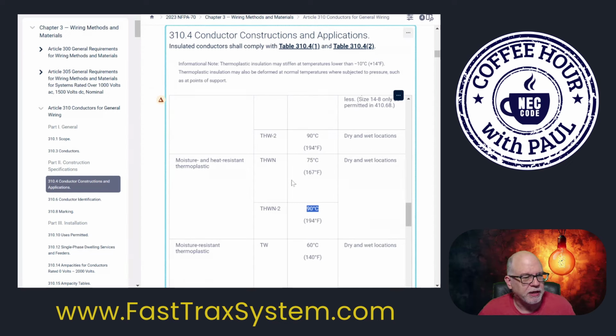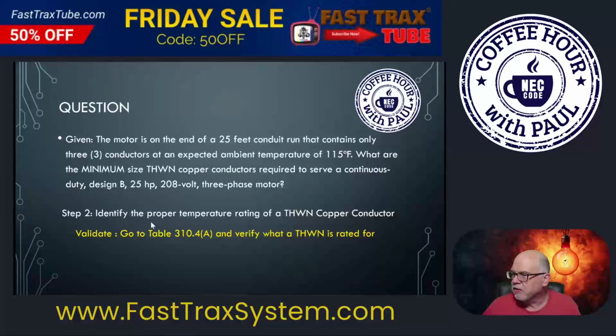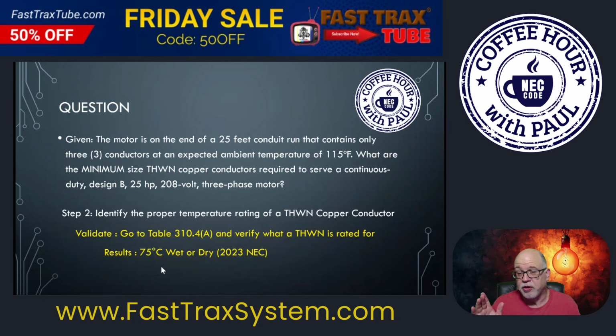So we know what we'll be working in. So we're obviously going to be right here in this 75. Okay. All right. So let's move on. So the result is 75, wet or dry, 2023 NEC. Again, whether you're following an earlier edition, it's still going to be 310.4(A) in the 2020 code. If you're in the 2017, it's probably going to be 310.104 in the NEC. Okay. Same information, just moved around a little bit.